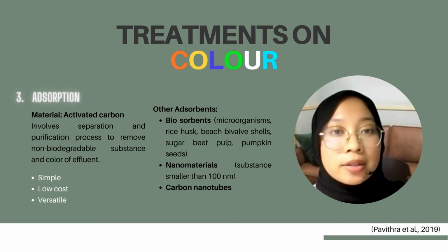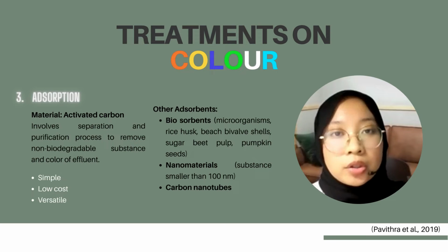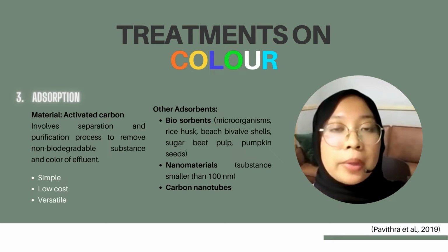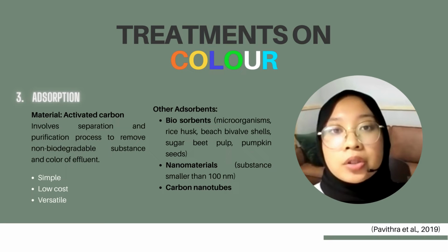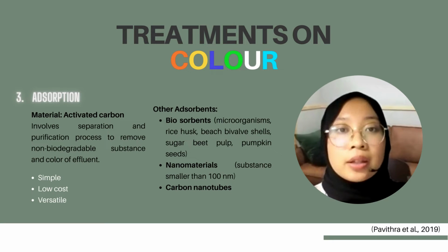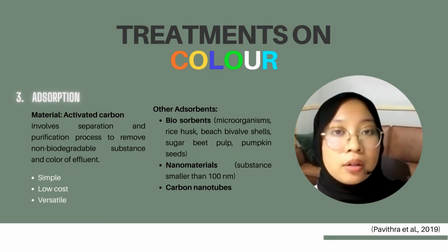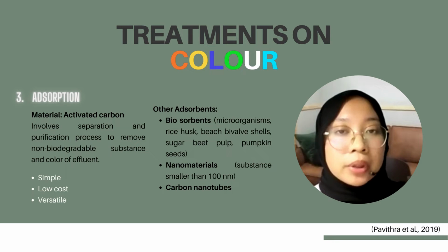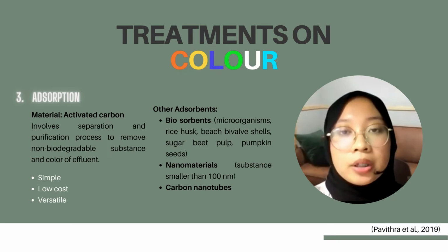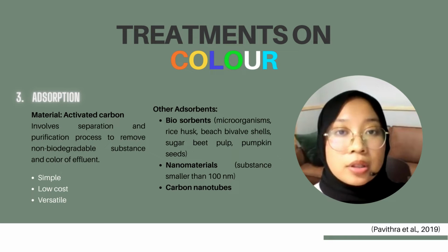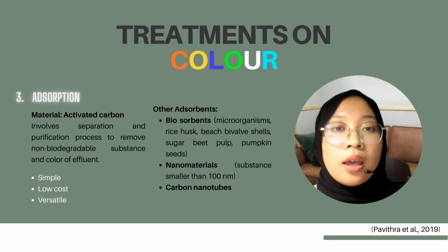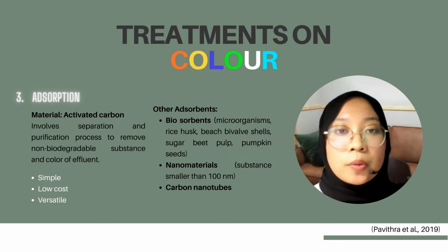Adsorption is the next treatment in which it can treat color in the wastewater by combining the process of separation and purification using activated carbon as the universal adsorbent. So activated carbon, the properties of this universal adsorbent will influence the treatment efficiency. But then we have other optional adsorbents such as biosorbents. The examples include microbes and also industrial byproducts such as rice husk, seeds, and also pulp.